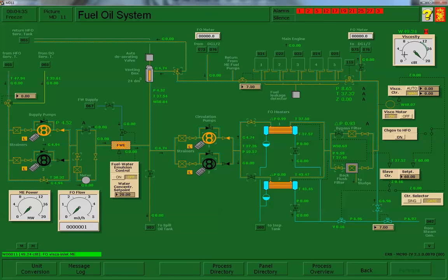Sometimes it comes up with pure distillate, sometimes it comes up with pure heavy, most of the time it comes up something in between. You have to deal with the fuel that you are given. So that's one of the constraints on this. But what I want you to notice is the fuel, 4.7 tons per hour, is flowing through this system, right? And it's going right back to the pump. So this is a circulating system. And then what I want you to notice is that there is 0 flow into this. This is just circulating right back to the suction of the pump. And that is through this regulating valve.